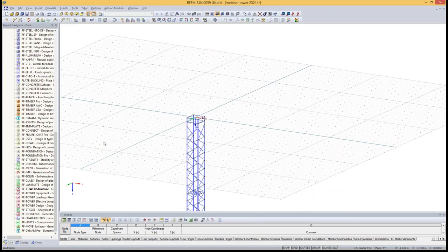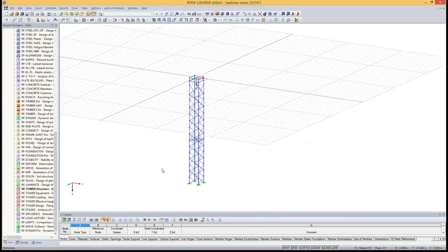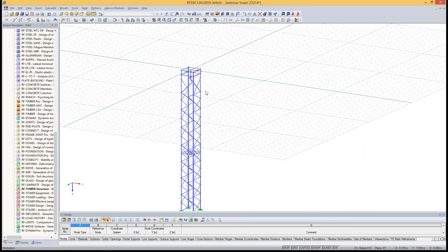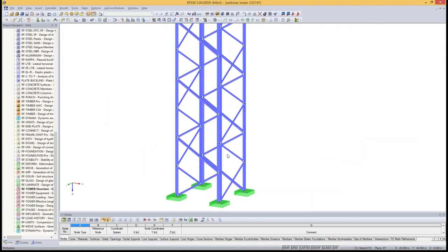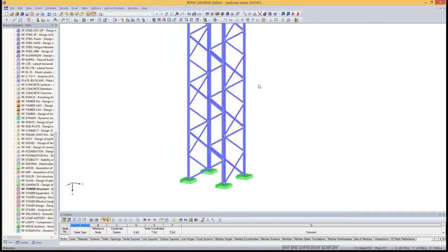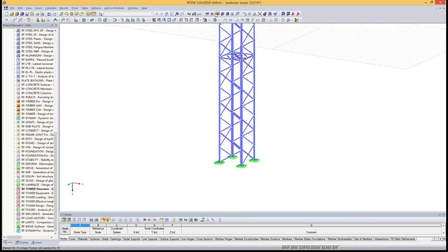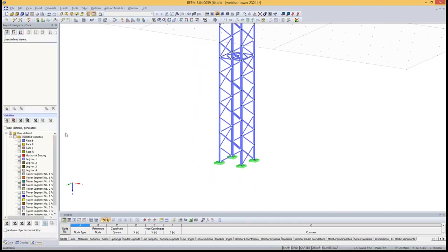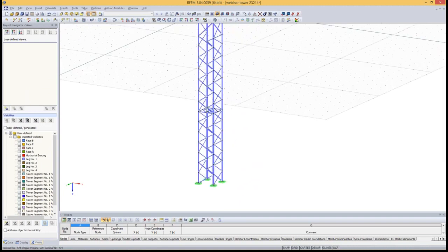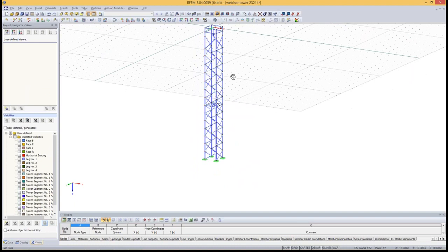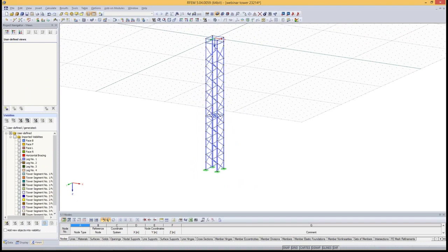Good. So now, as you've seen, I've exported the tower to RF-MAST, and to do it manually, it would take a lot of time to define all the members step by step. Another advantage of tower structure is that it automatically defines also partial views. We will see in the design of the structure later that you can check utilization ratio easily if you use these visibilities.